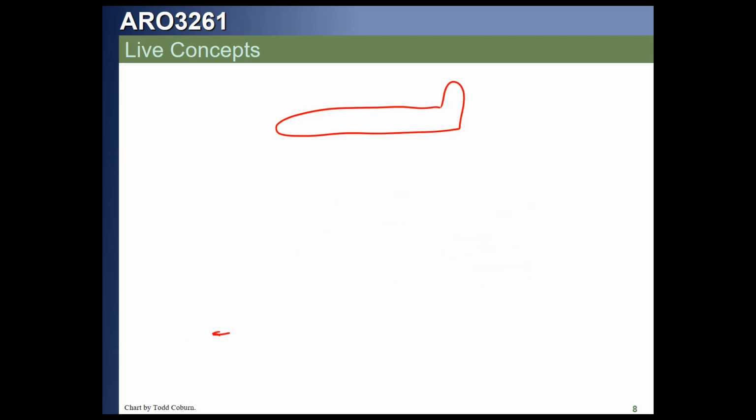Let's look one more time at a little element of stress like this one right here. If we have axial load on the fuselage, that's going to cause a component of axial stress. It's probably going to be compression. This is our axial stress due to axial load. If we have bending on any given element, we will also get a bending stress. This will be either tension or compression.